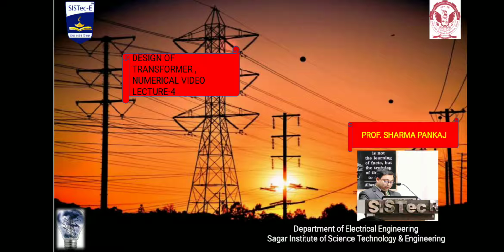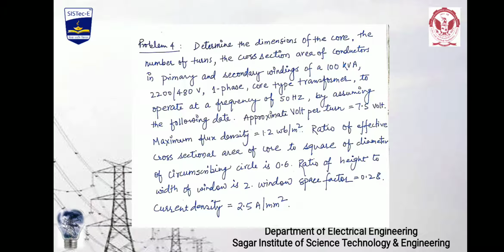I have given you a numerical in my previous video lecture to solve, and in this video lecture I will be giving you a detailed explanation with solutions of that numerical. Problem number 4 is: determine the dimensions of the core, the number of turns, and the cross section area of conductors in primary and secondary windings of a 100 kVA 2200/480 volt single phase core type transformer to operate at a frequency of 50 Hz.